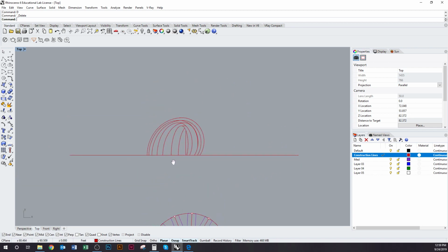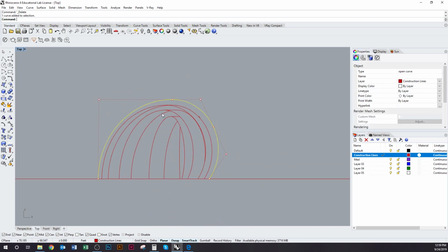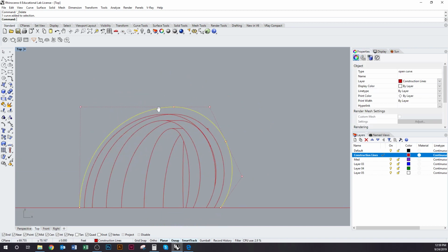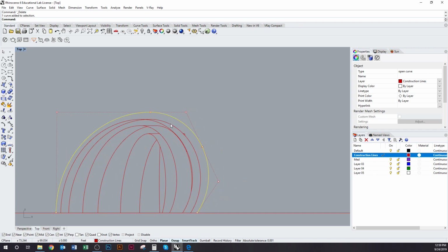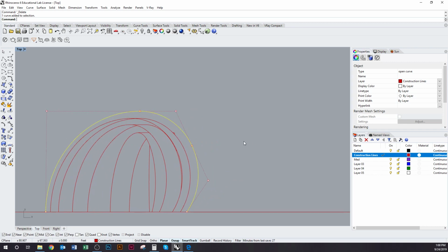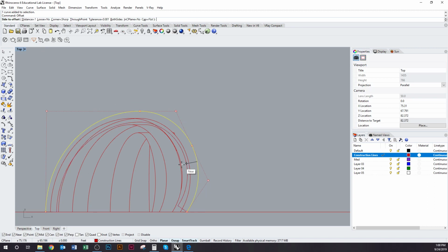So the first thing I would do here is actually add thickness to each of these strips. Obviously, they wouldn't be zero thickness in reality. So what I could do to represent the thickness would be to offset the leading edge of each curve, the outside edge. I'm going to use the command offset, and also the option cap. If I click on cap and select flat, you can see that's also connecting our original line with our offset line. Distance, I'm going to choose maybe 1 inch.